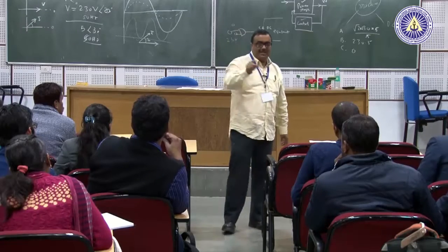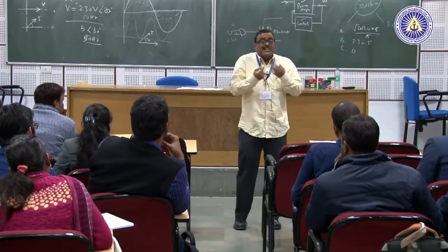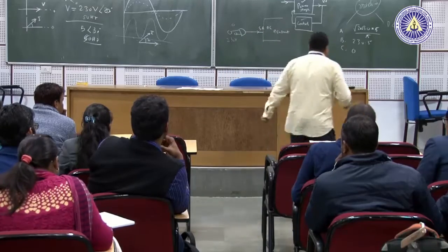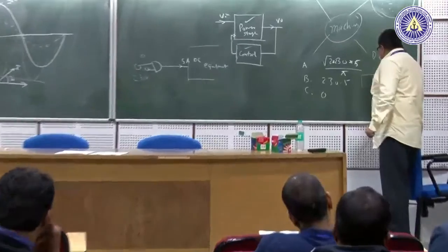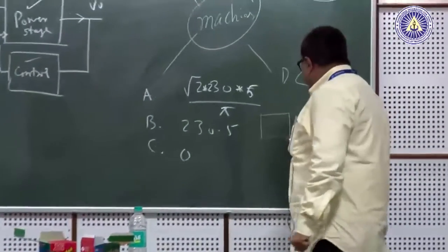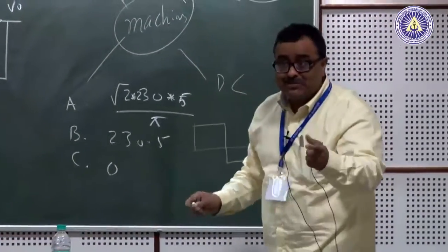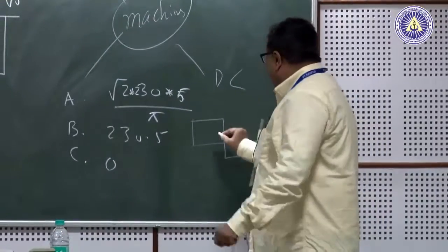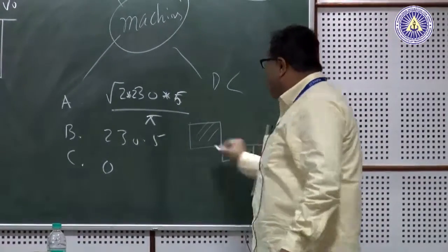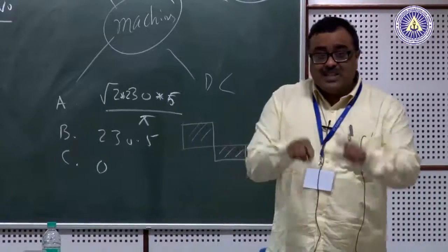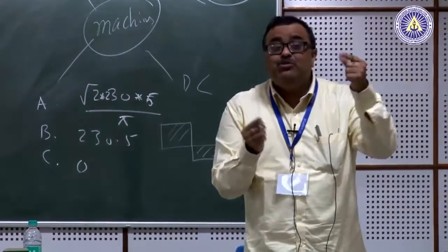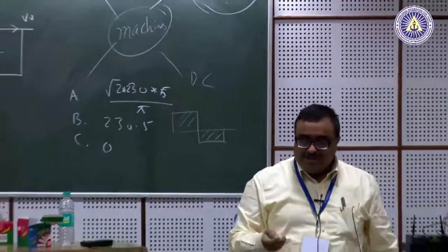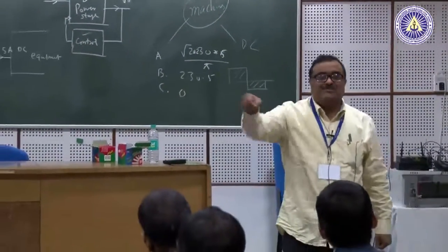So that you eliminate that DC, because you are now recreating a waveform, right. What you have done is that part of the time my output will be plus 12 and part of the time my output will be minus 12. You have a 12 volt battery. Now, who makes sure that these two areas are the same? Because unless these two areas are the same, the average will never be 0, right. So, who makes sure of that? No one makes sure, that is why you have to put a transformer there.